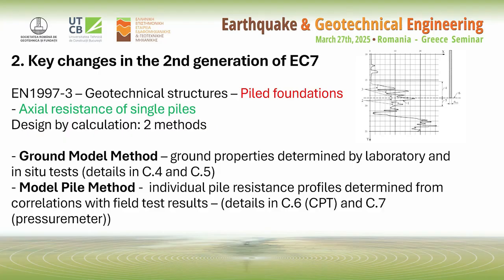In terms of the resistance of a single pile, two methods are defined, and I agree with some of my colleagues that maybe the names are not very suggestive of what is inside. One is the ground model method, which is based on ground parameters determined either by laboratory tests or by in situ tests. And the second method is the model pile method, that means based on individual resistance profiles determined mainly from CPT or pressuremeter.